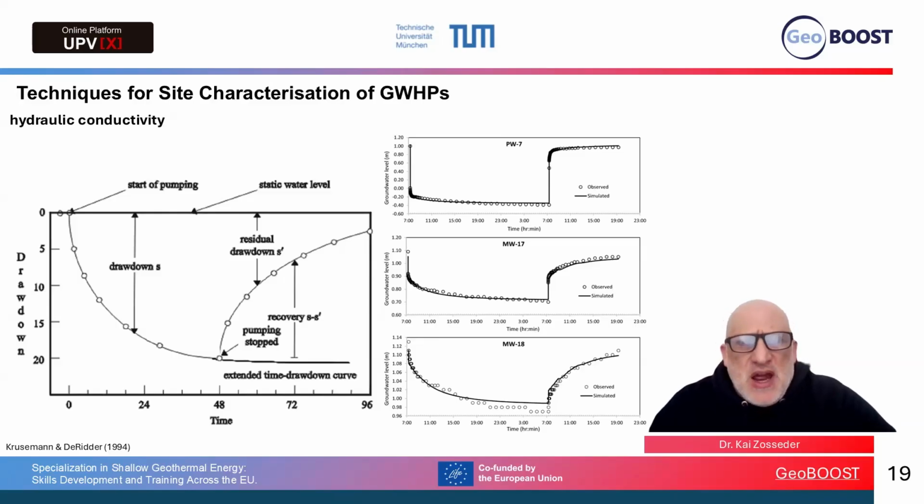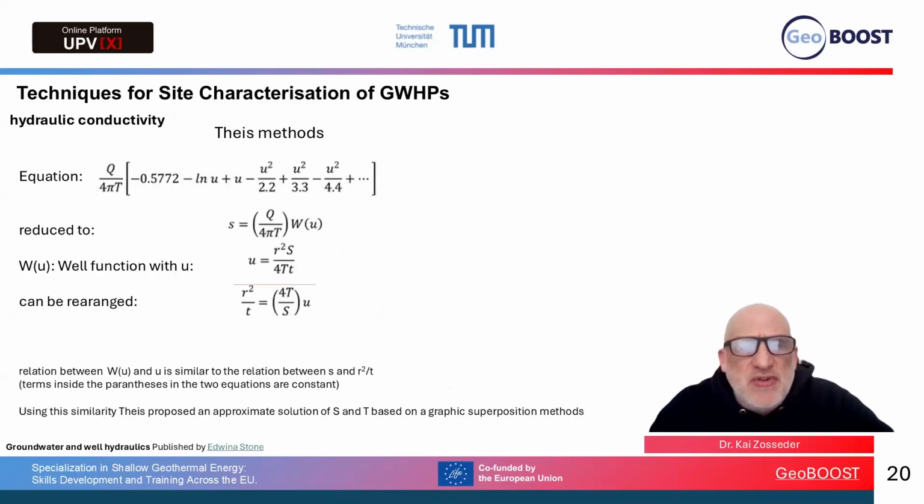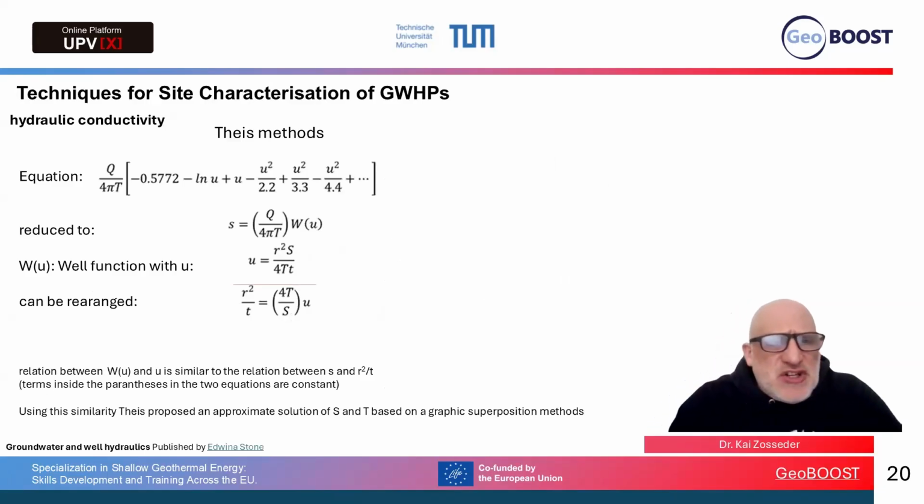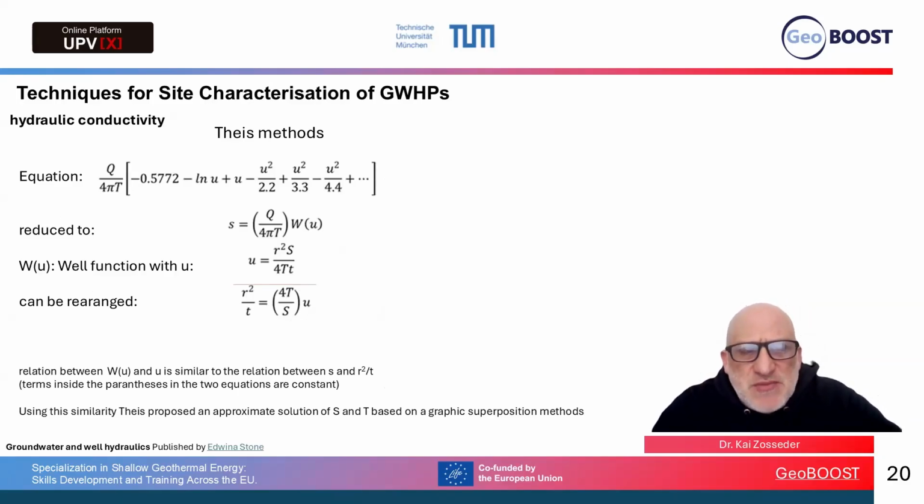conditions there. And so by this relationship between drawdown, time, stable drawdown and also the pumping rate, we can calculate our hydraulic conductivity. This is the Theis equation, so you don't have to go into detail here. But with this equation there is the relationship between transmissivity and drawdown, and what is also important is the storativity. So how much water can be stored, or is stored, in the underground. This is also a value that you have to know.